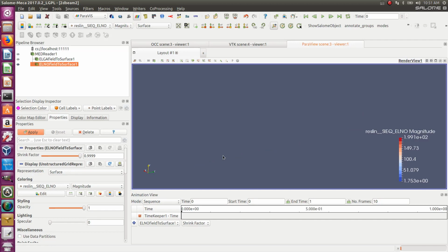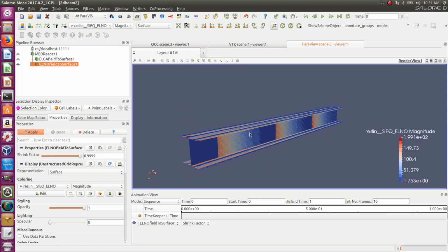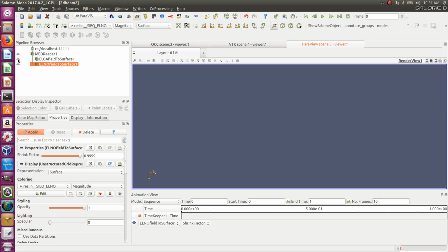Well, that's not what I expected to find. I'm getting a stress field which is really strange. But the problem is that this is a normal result if you use this method, which means here I'm not using the right visualization method. That's why I'm getting this kind of thing. What I should do is something else. I should use a different kind of visualization.